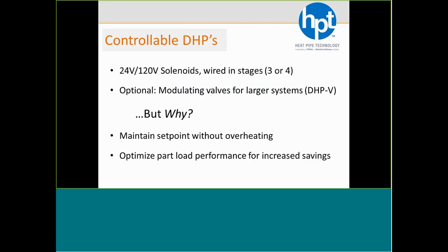Like anything, you hear this argument on the chiller side and other equipment all the time. Why size it for the time where you're spending the least? Why not size it for those part load days where you're spending most of your time? Get as much performance as you can, and then on those peak days, just start shutting off circuits so you don't overheat the space, but you're always maximizing your performance.